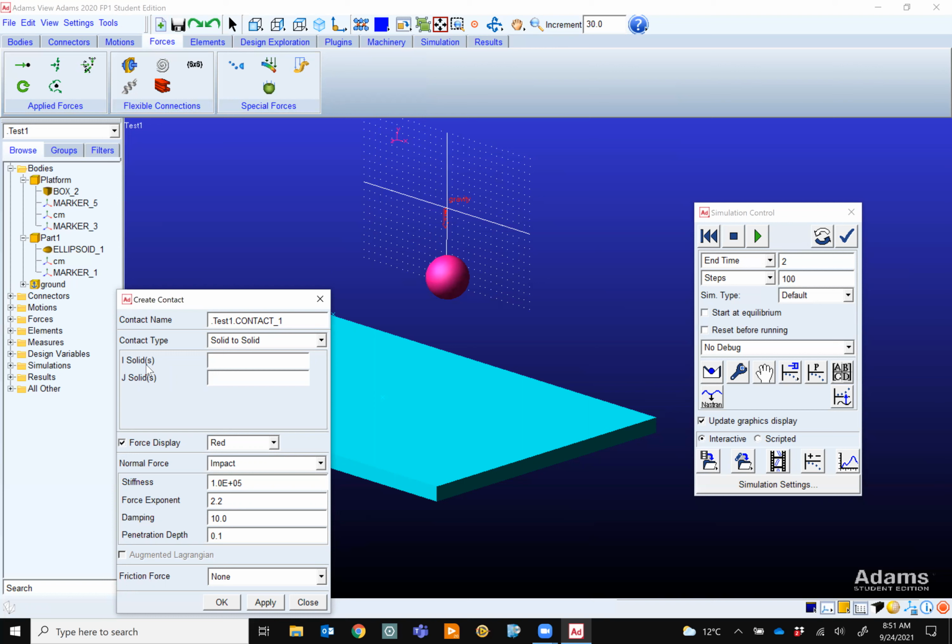And that area, you can model it as a spring and damper, because there is more like a spring and friction between these two. And it's not just a ball, it can be any solid, like even my laptop and this table. The contact between them is a spring. But that spring, of course, has a very, very high stiffness, so I cannot press it down.